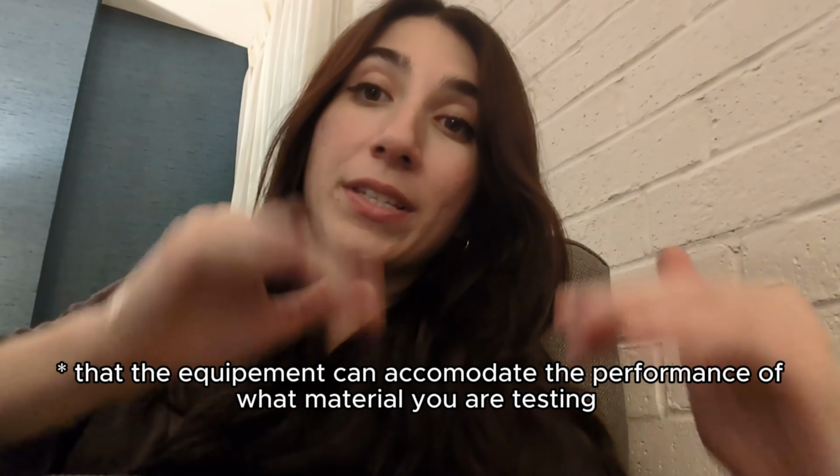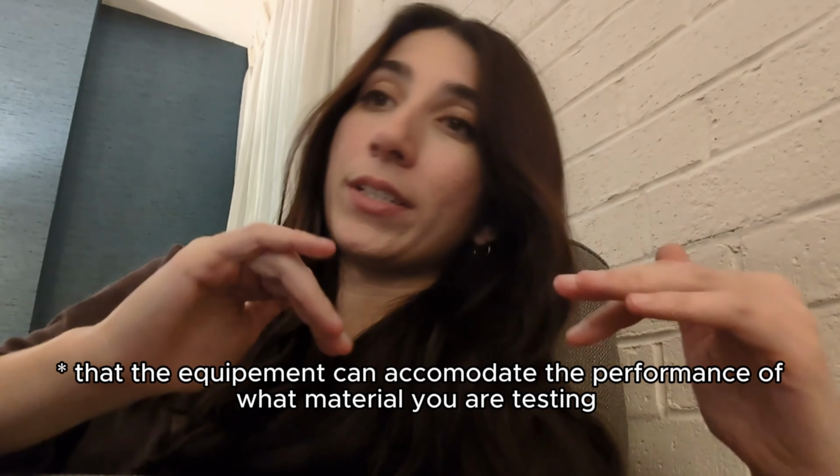What I'm trying to reiterate here is the importance of using testing equipment that is built specifically for the material you want to test. TPU in this case is a rubber-like material. It's able to stretch clearly above 300% of its original gauge length. So with the automated solution, it's purpose-built for that type of material, as well as the standard we're using, and it has the proper extensometer tools, a video extensometer, so that the full strain range can be measured.